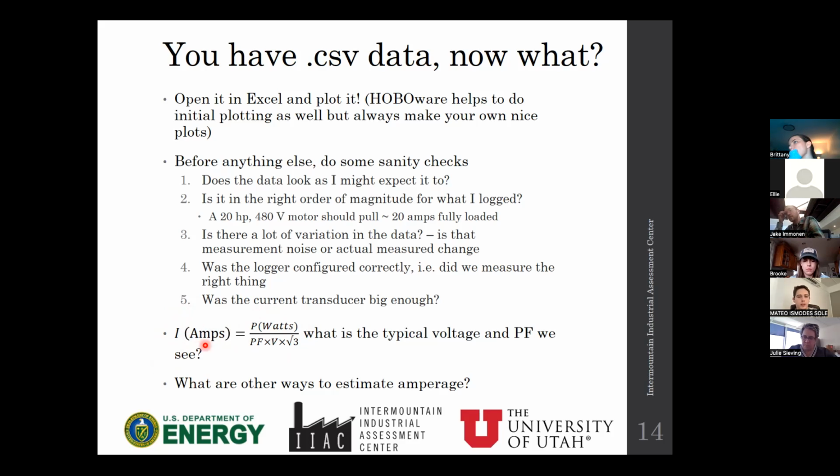I think in the equation, the power factor would usually be the power factor for the entire facility, right? Like the one we get from the bills, and then the square root of 3 is the approximation, because we usually get this data from one of the cables connected to the system, right? Yeah, and then the square root of 3 would approximate it for the other two. And I forgot to mention the power factor. The power factor is usually what we find on the bills.